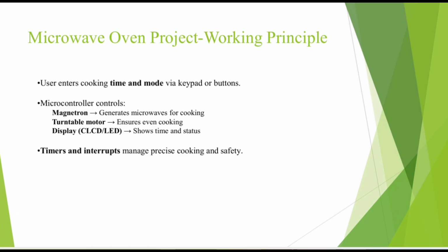But with the help of PICSimLab, how will it work? So, we are simulating a microwave oven project using PICSimLab. The PIC controller is the brain. It reads input from buttons, controls the magnetron power, updates the display and handles safety features like door interlocks. The simulation lets us test all this logic virtually before moving to real hardware. It is a great way to learn PIC programming and test ideas quickly.